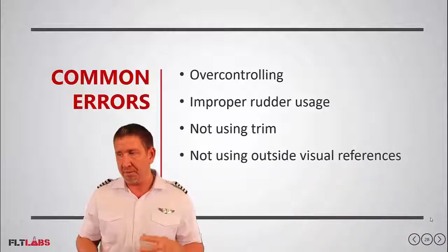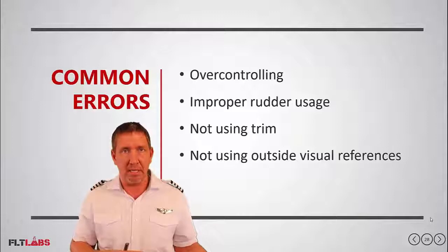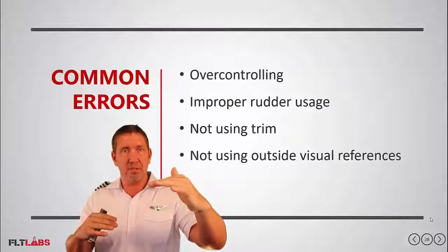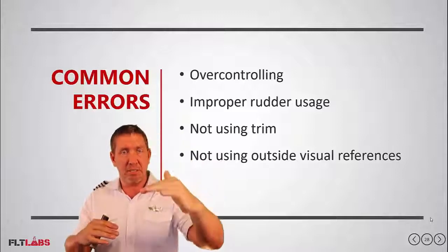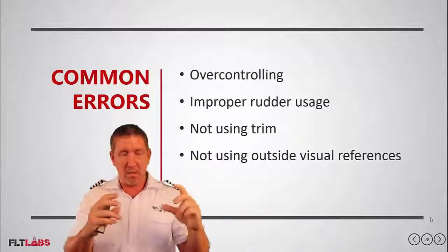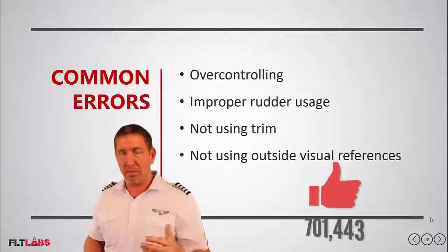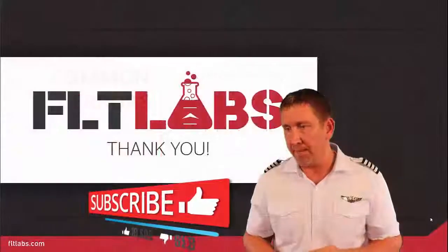Not using outside visual references, we've already discussed it. Very important to set that, because using the outside visual references, you get to see changes in your pitch attitude much easier than looking at the small attitude indicator in the plane. So definitely super important to do that.